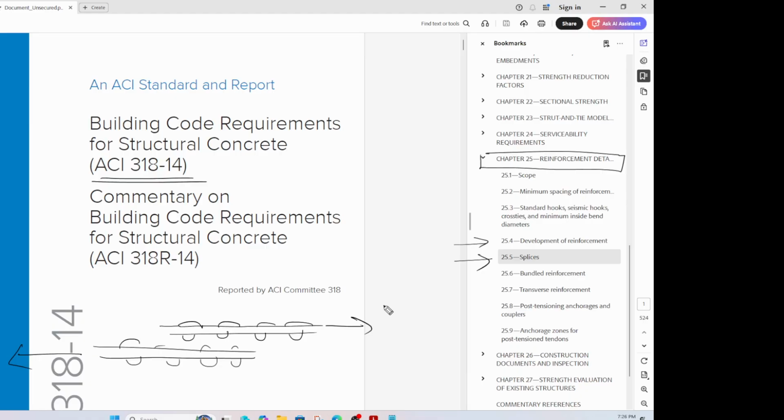So you want to translate the tension here. The whole thing is surrounded in concrete. So imagine concrete here. Imagine these are the reinforcement bars which are embedded into your beam or a slab or somewhere. So you want to transmit the tension force from this bar onto an adjacent bar. And the way to achieve this transfer is to splice them. Right.